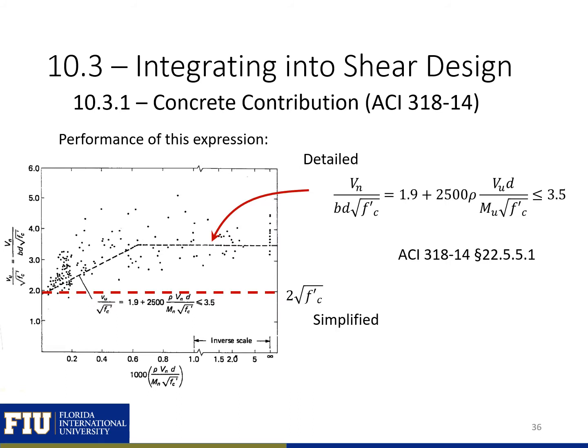And we can see on this slide how that detailed expression lines up with our experimental data. So the detailed expression here is this dotted line with all of our experimental data. And we can also see where our 2 square root f'c lines up with the experimental data. So this is the simplified shear expression for non-prestressed sections.